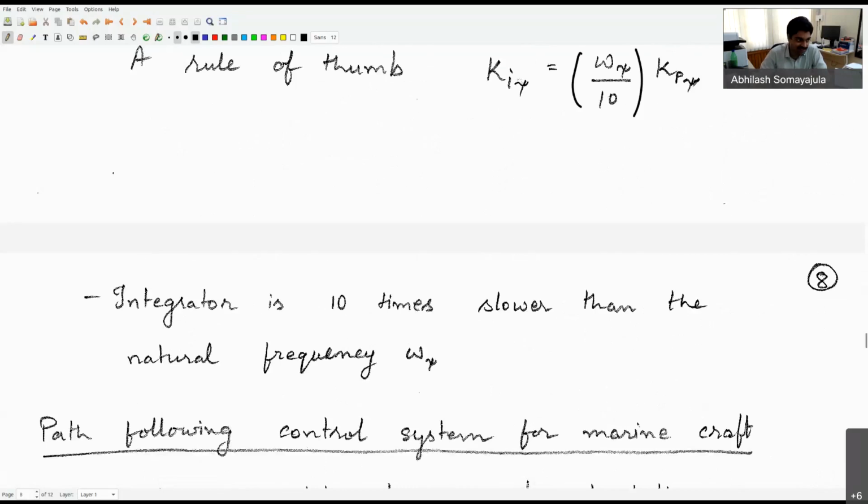Okay. If our integrator is responding too fast, then it is picking up errors very quickly and can lead to large overshoots, which is what we looked at with the idea of integral wind-up a few lectures ago. Right? So in order to avoid that, we want our integrator dynamics to be slow enough. So a good thought process is that it should be at least 10 times slower than the proportional gain, and we can choose that ki value in this manner to make that happen.